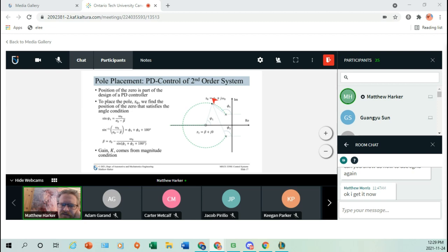on my locus, that's going to be my test point, my S0. It's going to have an angle to the original poles. So pole 1, pole 2, these angles are then fixed. And basically what I would then do is have a variable third angle, and I would need to find the psi1 that basically moved my locus to where this point lies on the locus, right?